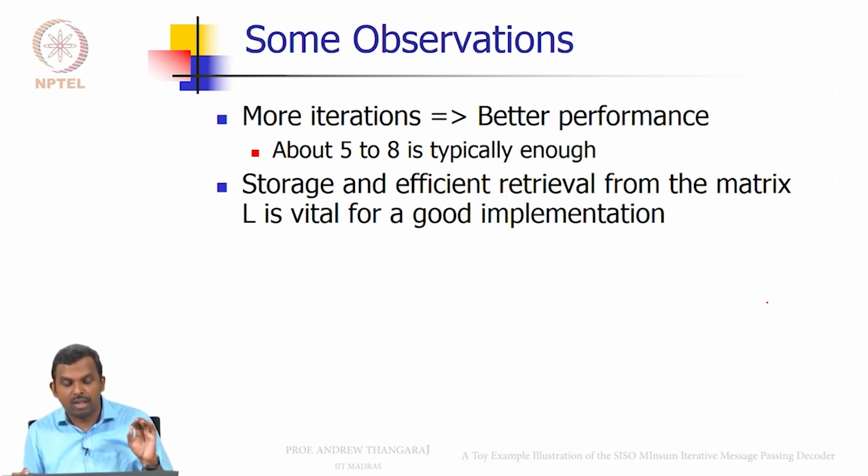Storage and efficient retrieval is the biggest challenge. The computations are not the biggest power consuming, area consuming implementation constraints for the LDPC decoder. Storing the entire L matrix and efficiently reading and writing into it in parallel is an important constraint, but today people have very good implementations working at very fast rates. So, that closes the example and a discussion on the decoder for LDPC codes.